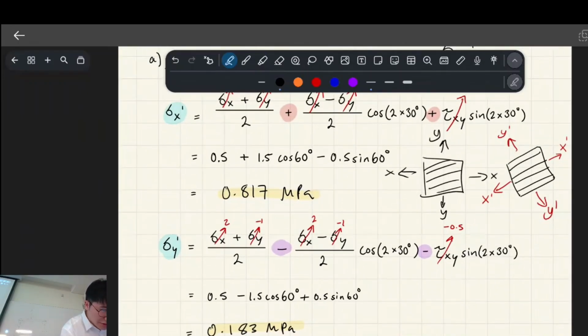Oh, the other thing I forgot to mention is when you have a stress element, right? Basically there's typical positive and negative directions. So going away from this 2D stress element is positive, right, in tension. And going in is compression, right? So that would be a negative value. But what's less intuitive is the direction that you'd notate for shear stress. So going up and right into that corner, that's positive. And down and left, so that's the positive convention for shear stress. The negative would be the opposite, basically. So that's the negative convention for shear stress. Okay?